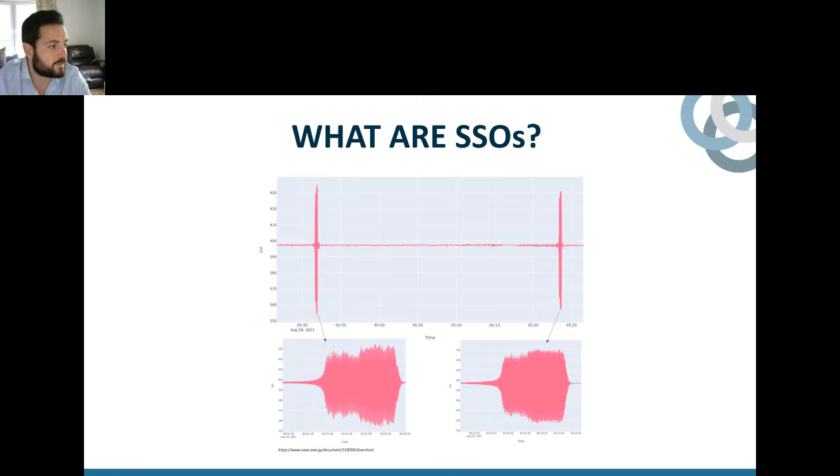On the zoomed-in plots at the bottom, you can see how the oscillations build up quickly, reach significant amplitudes, and then they fade away again. And they faded away because of the introduction of damping from the synchronous generators. Now, these are the kind of oscillations that are undesirable because they place additional stress on equipment, and this can cause protection systems to trip, and in the worst case, may threaten system stability.